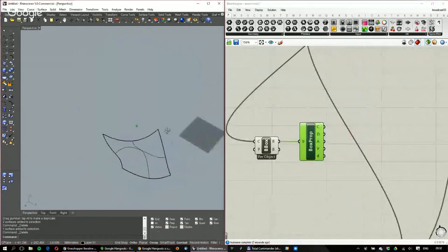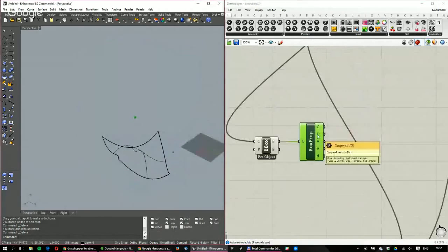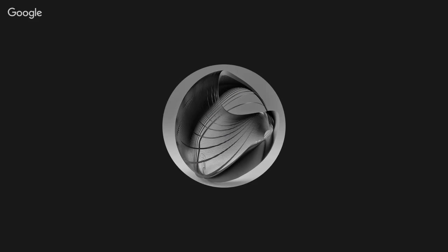Central point of the box, and this is a diagonal. We can use those to create a sphere. So sphere, this is a bounding sphere. Now this is a bit too large, but let's keep it like that. Maybe we can divide this or multiply. Basically, we should multiply it by 0.5 because we only care not about the diagonal, but half of it. But let's make it slightly bigger.